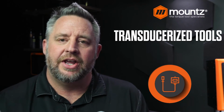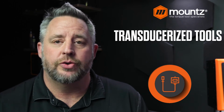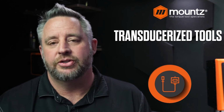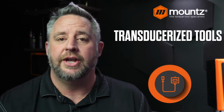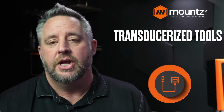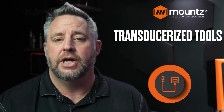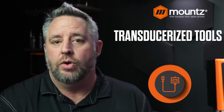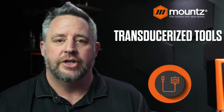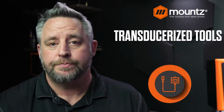The next that really helps with this is the use of a transducerized tool. Basically what that means is there is a built-in sensor in the tool that is monitoring the actual torque output. There are different types of smart tools that will be either a current control product, where the torque is converted from the amount of current that is being used.